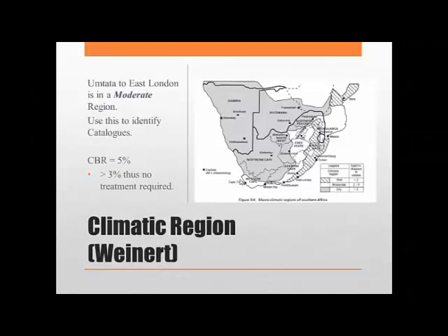CBR values would be determined, for example, with a DCP test and the like. For contextual purposes, this information will be issued to the student. The minimum requirement for a subgrade is CBR of 3 in dry conditions. In wet areas, a minimum soak CBR of 3 would be required. Values of less than 3 would need to be treated. Just to repeat, the student would be issued with the subgrade information, and also we would work with an assumption that the subgrade would be the same, consistent for the entire length of the study area.